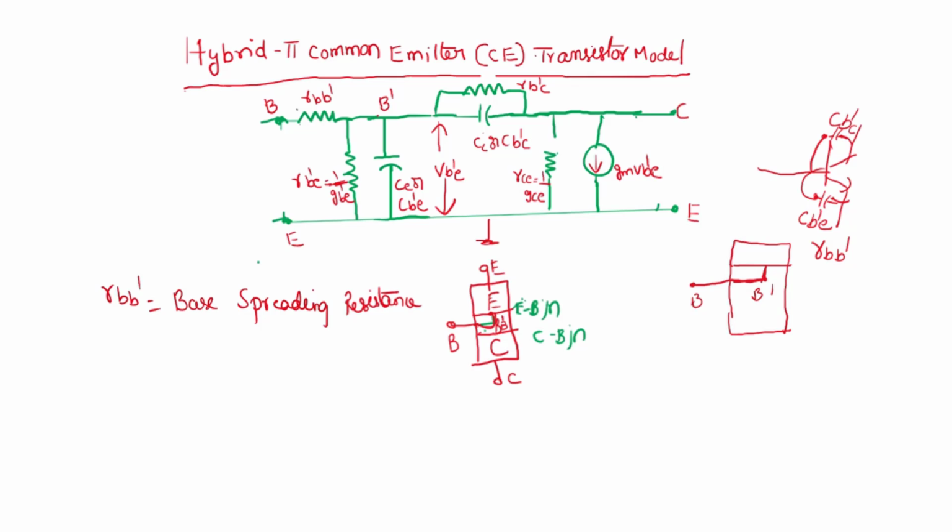For CB'C also, the resistor RB'C helps it to charge or discharge. Here the resistance RBB dash is supporting CB'C, and only then can CB'C act. All capacitors depend on some time constant, and the time constant of a capacitor is RC, R into C. So where is the resistance for this capacitor to act? Now RBB dash comes into the picture.